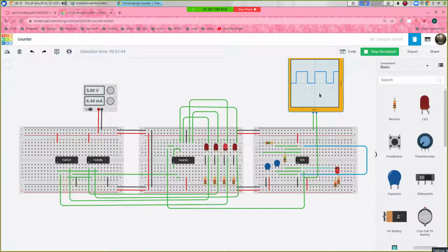So what I have this set to right now is half a second per division. So half second from here to here, half second to the next line, half second to the next. And in really small print down here, you see 5.00s. That means the entire display is 5 seconds. Now normally oscilloscopes are used to capture information that's changing really rapidly, usually too rapidly to see, like something changing 100 times a second.